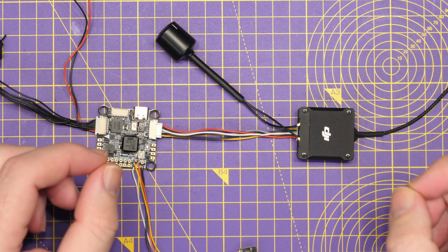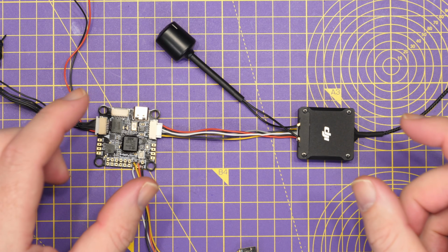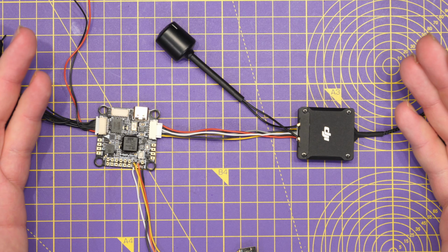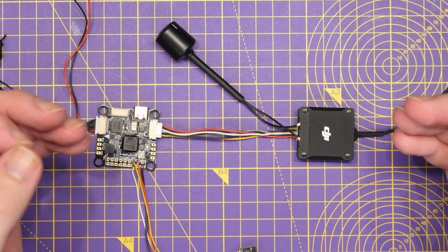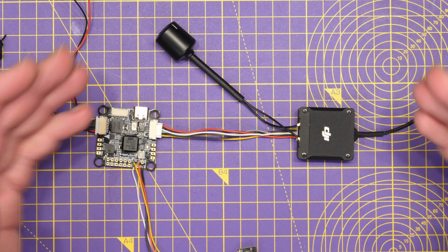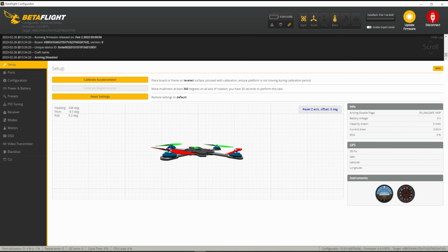Once that is done, you need to then configure the MSP options on your flight controller. In Betaflight, whether it be 4.3 or 4.4, this is simpler today than it's ever been via the preset options, and I will show you how to do that now. In the past, you had to mess around with the ports tab as well as some command lines. However, today, things are much simpler simply as a result of the new preset options that are available in Betaflight.